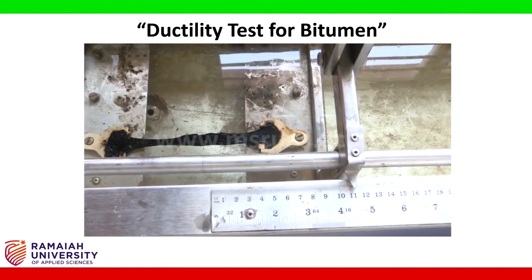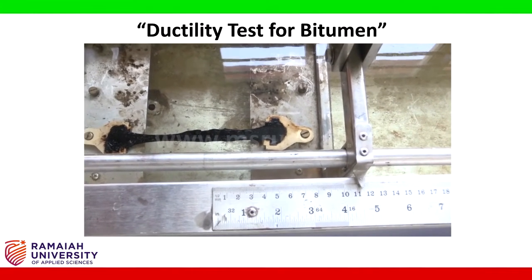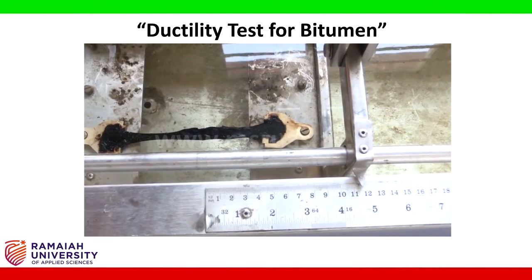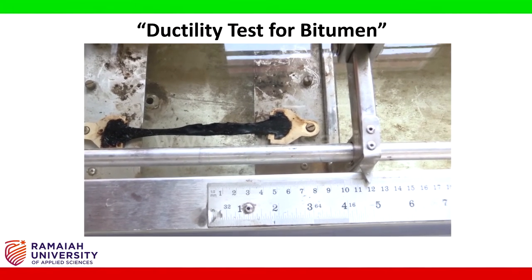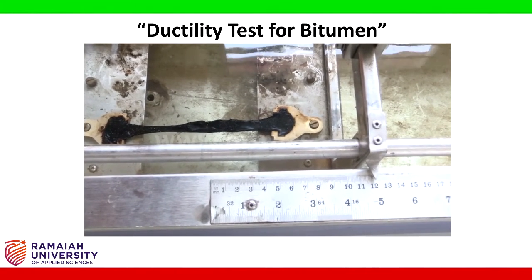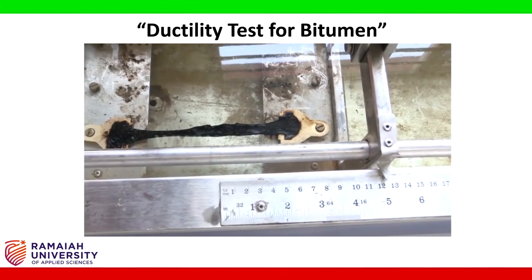That particular reading will be taken as the ductility value of the bitumen. On the second condition, if the thread is not going to cut and it elongates beyond 100 centimeters, the ductility value of the bitumen will be taken as 100 plus.